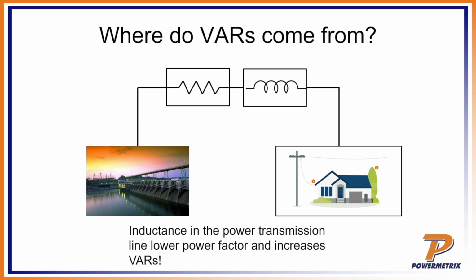The lower the power factor, the fewer watts are going to be generated and the more VARs are going to be generated. Once again, we as a utility typically want to maximize the watts because that's what we're being charged for. And so a lot of times what we'll have to do to compensate for that inductance is we can add capacitance. Inductance and capacitance are duals in the realm of electrical engineering, meaning that one can cancel the other. Really what we're doing is we're compensating for that phase angle and trying to bring that back to as small a phase angle as possible, as close to being in phase as possible for the voltage and the current. So that's what that is.